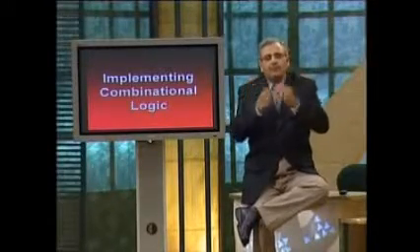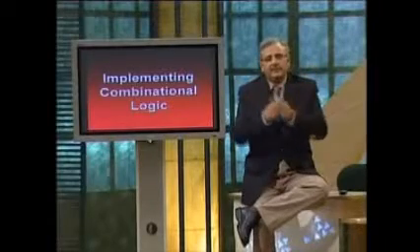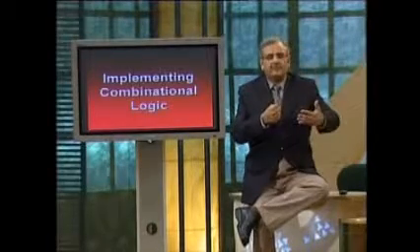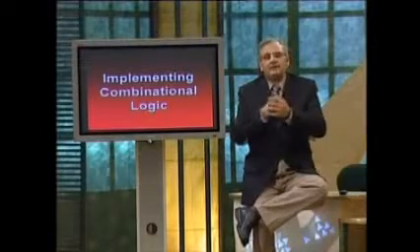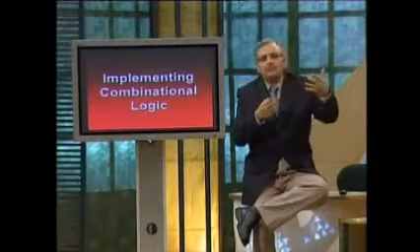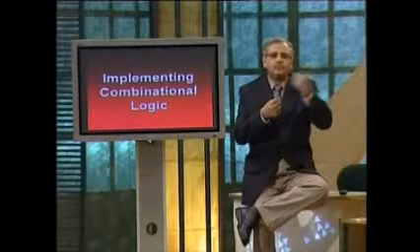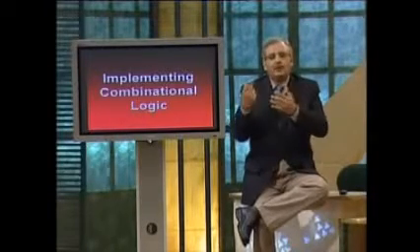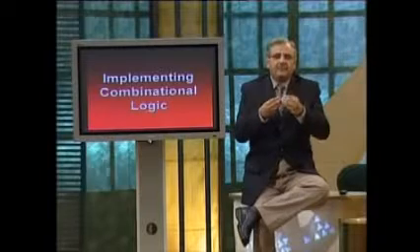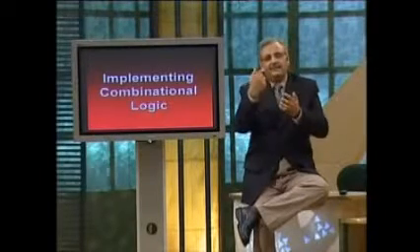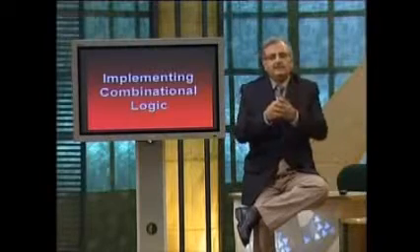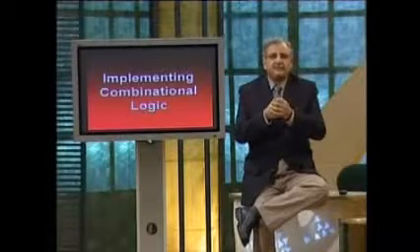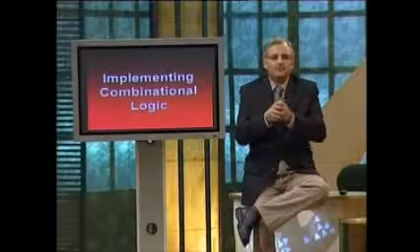Okay. How would you represent the function? Basically, you would draw out a truth table where you would have all the possible inputs and the outputs. Now, how many inputs do you need and how many outputs do you need? Basically, you need 4 inputs representing the 2-bit numbers and a 2-bit output. The adder, of course, also generates a carry, so you need another single bit output representing the carry. The adder might also add a previous carry, so it needs another carry input pin.